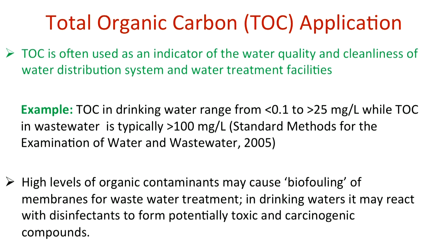And what's the importance of determining the concentration of natural organic matter? In wastewater treatments, as well as drinking water treatments that employ membranes, it can cause biofouling of these membranes. And also in drinking water treatments, it reacts with the disinfection chemical, the chlorine, to produce potentially toxic and carcinogenic compounds.